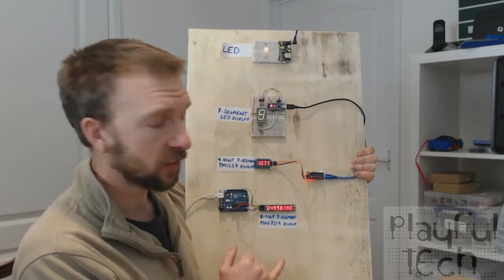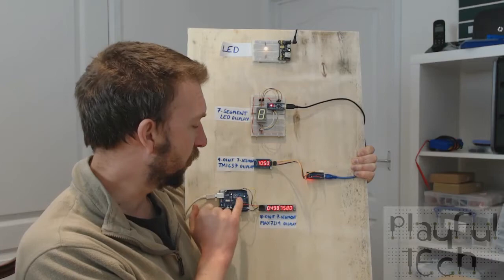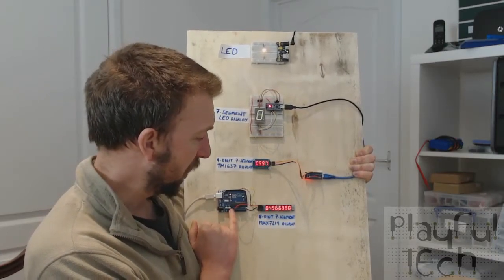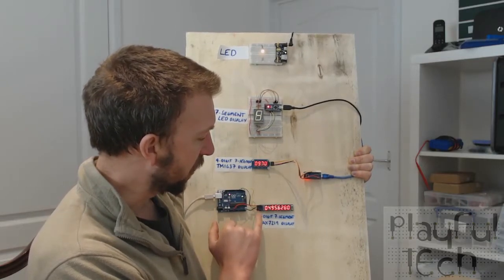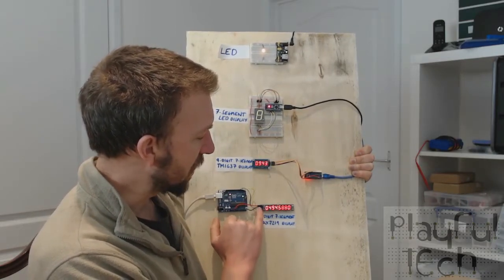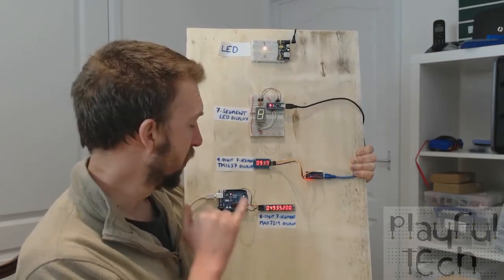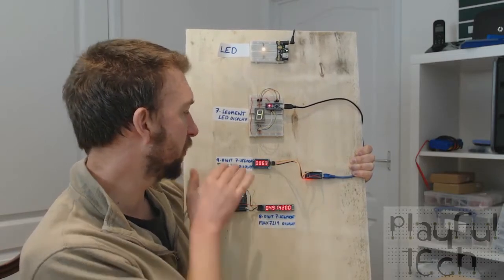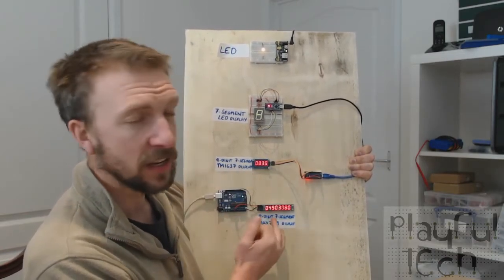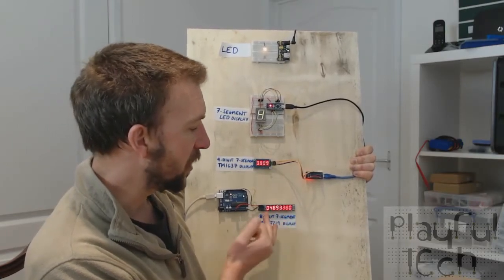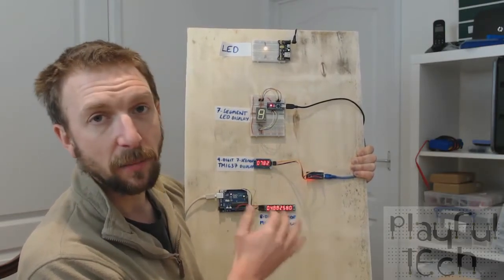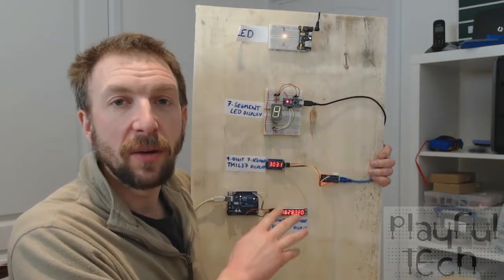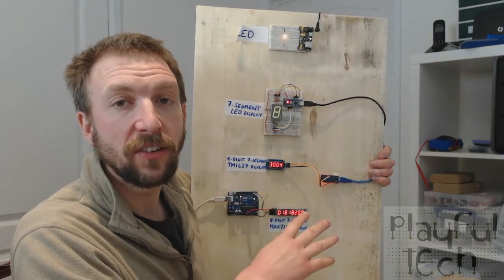And this one has 5 pins. So again, voltage and ground. This one is a 5-volt display, so I've got the 5-volt plugged in here. And then it has a data in, a clock, and a select pin as well, which are just wired to my digital outputs there. And just like in the 4-digit display, each one of these characters can be individually controlled to display a number or text.